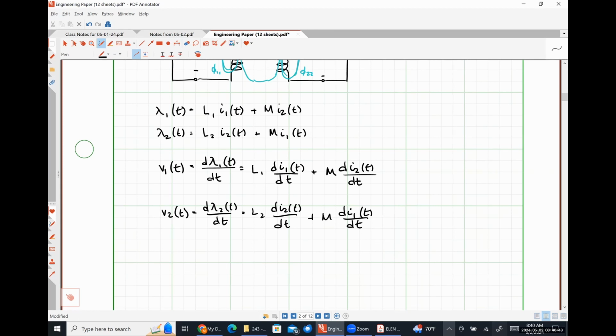The dot convention is effectively a requirement, at least for schematic diagrams, because it is not easy to convey the direction that a coil is wound on a circuit schematic. So we use a dot convention to take care of that for us. Before we do that though, right now we have everything in the time domain. We are not going to analyze any of these circuits in the time domain whatsoever because that math is entirely too gross. Instead, we're going to analyze all of our circuits in the frequency domain.